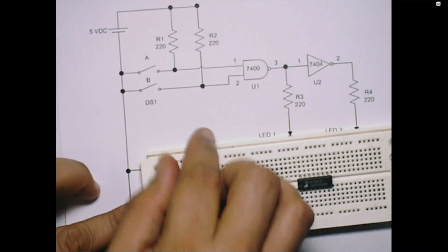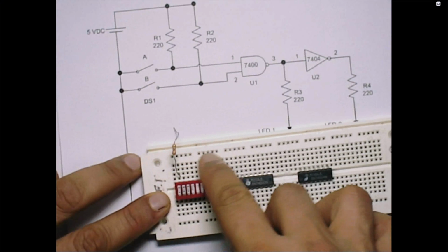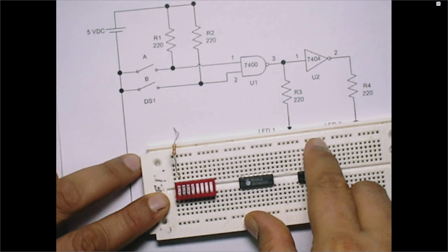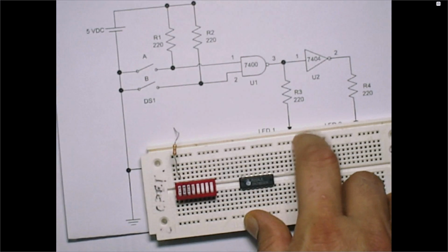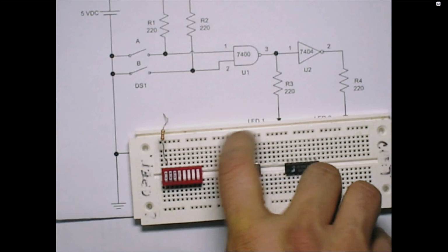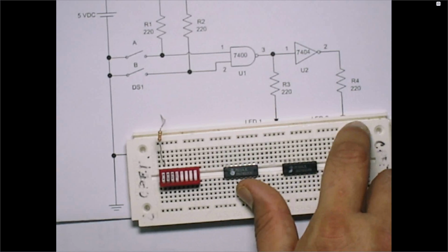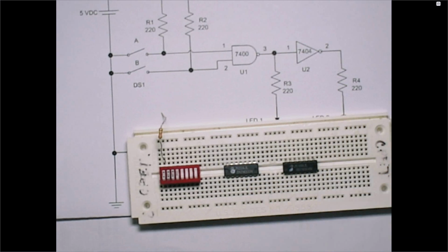And this is my power. This rail here is actually for the power, meaning anywhere we need power, we connect into this row. This row is shorted, so we connect to this row, and this row will be connected by one pin to the power station. Remember, when you go to the lab, you will have a station with a 5 volt power supply, right? You will connect the 5 volts to this row.